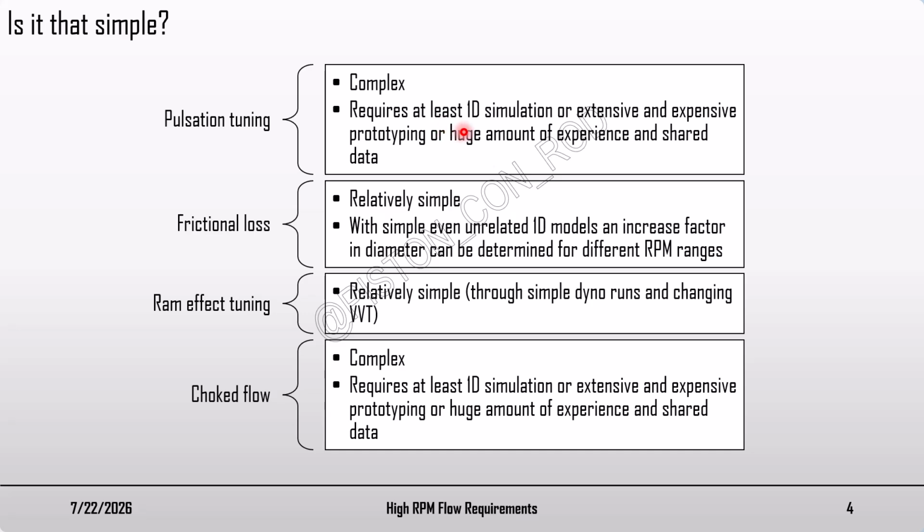And for its calibration, you need a lot of data and some complex data, which requires very expensive measurement devices, or you use some consultation companies for that. Or based on your experience tuning engines, if you have been able to work on different engines, you'll definitely find the best values for similar engine setups.